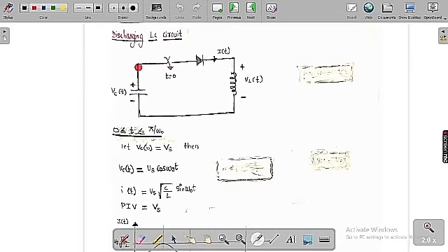So the capacitor is going to deliver the current in this manner. Now see, this is called a diode and this is an inductor. So this is plus or minus VL of t, plus or minus VC of t. Before the switch is closed, I am going to assume the capacitor has some initial voltage, which is, let me assume, VC naught, equal to Vs, in this case.